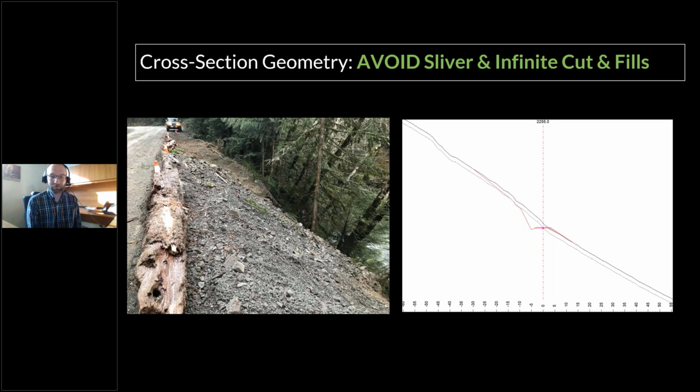And I say that because, well, maybe you'll require special equipment. So maybe you have to mobilize in an excavator with a long boom to build what you have designed. So that's going to be a cost. Or maybe it's that you need to build a tote road, so a temporary access road to either get to the top of the cut or get to the bottom of the fill to make a foundation to build off of, or just to get within the reach of your machine. So both those options represent a significant cost. And I'm not going to show it, but you can design your tote roads if you'd like.